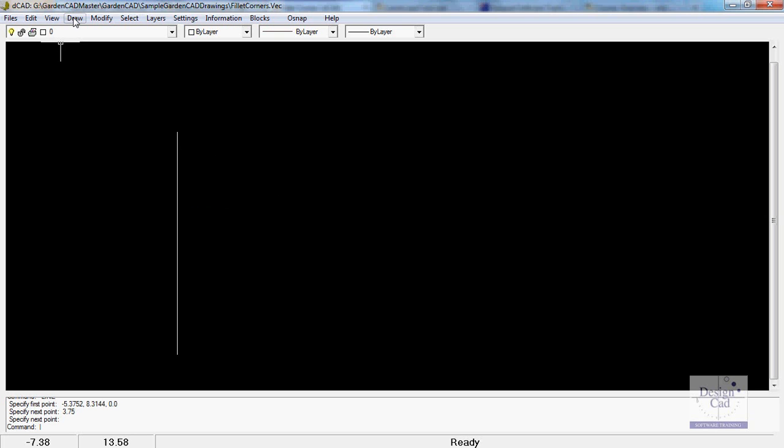Let's do that again. I'll draw a line, but this time I'll press the F8 key before I start. And now I'll set my start point. See how as I move up, I can't track straight up. I press the F8 key again, and now I can track straight up. So I'll draw a line, this time 4.5 units long, and hit the right mouse button to finish.